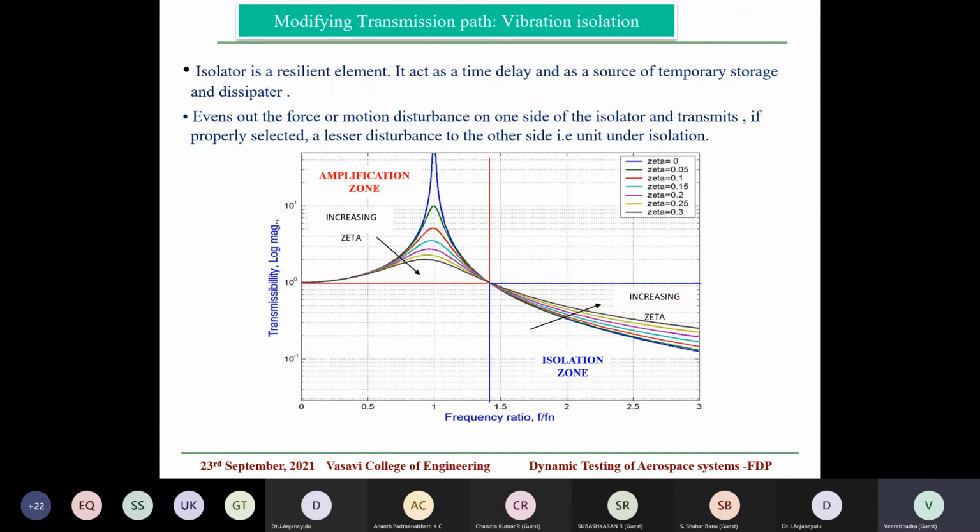What we mean is, suppose you are using a rectangular box that you want to isolate. You will have four corners, and generally four mounting points. If you select four isolators without checking, the natural frequency may vary within plus or minus 0.5 hertz, which is okay.